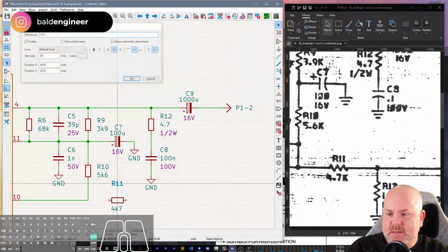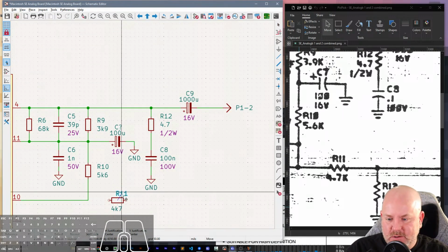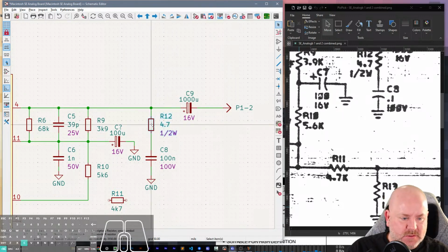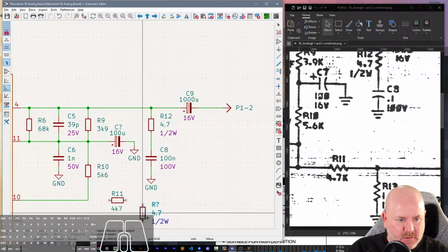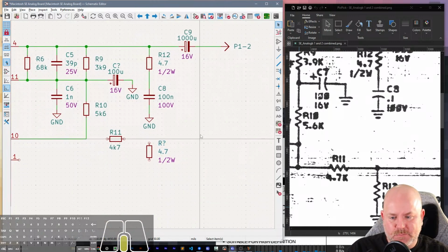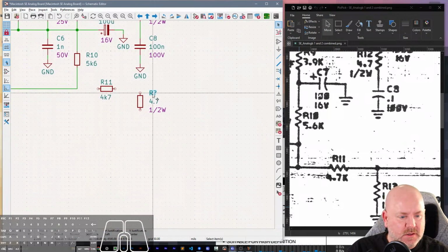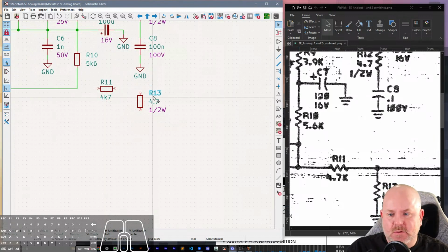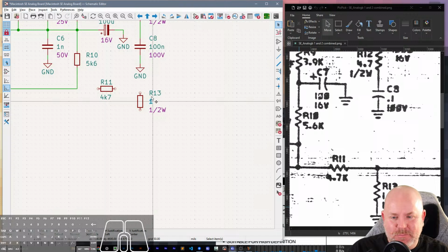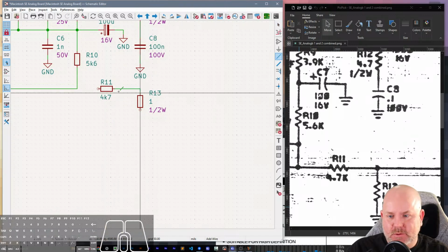And we're going to make this be 11. Move this down here. And then we're going to copy this resistor since it has the power on it already. And this roughly goes right here. So let's middle mouse button to drag everything. And then we'll do R13. 1 ohm. That is not adding many ohms. Put this over to here, put this to here.